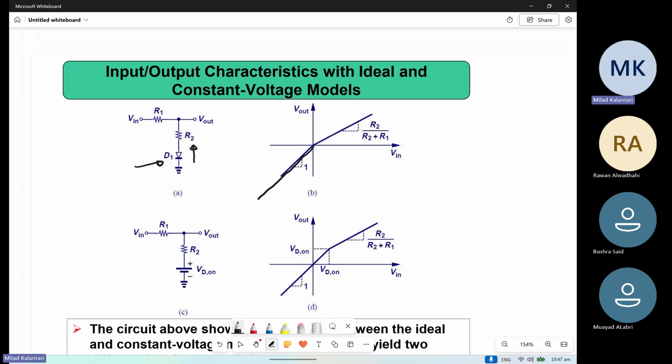So once the V in is larger than 0, the current starts rotating back this side. And then the diode can turn on, right? Once the diode is on, ideally the circuit would be what? Like this, just a voltage divider, V in, V out.